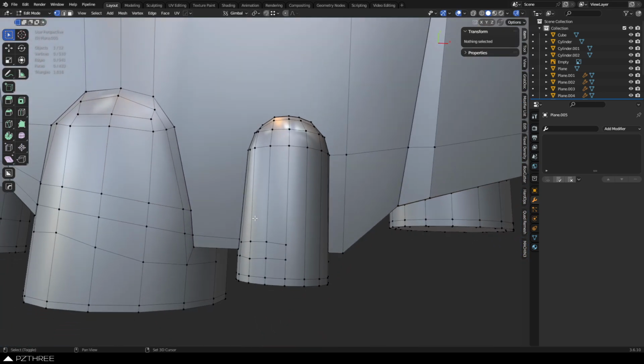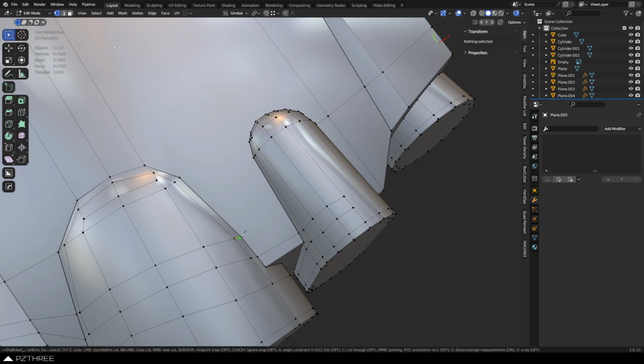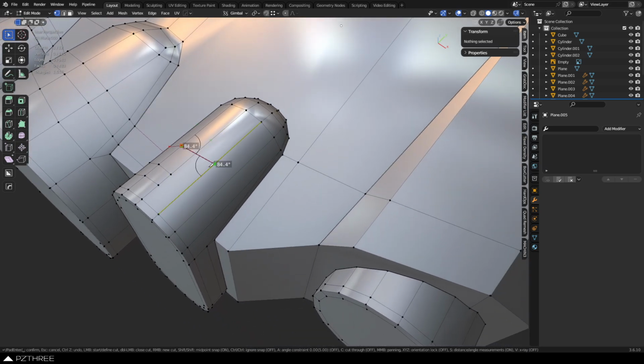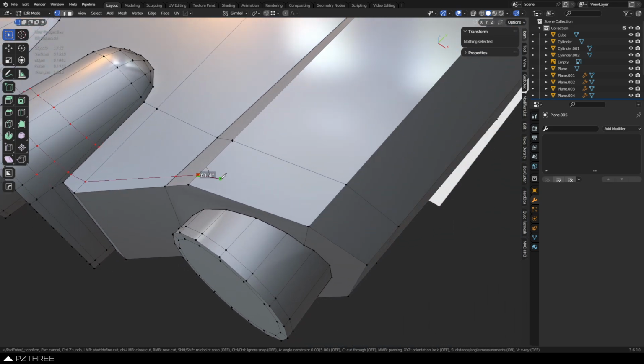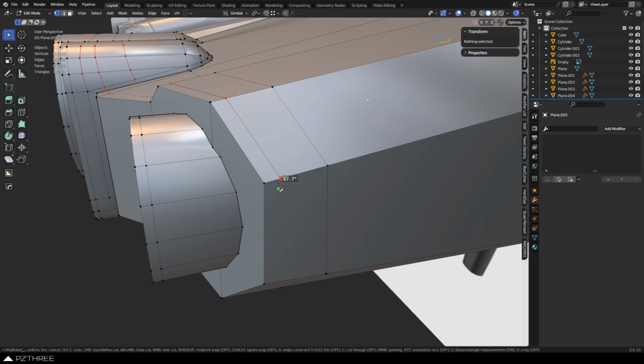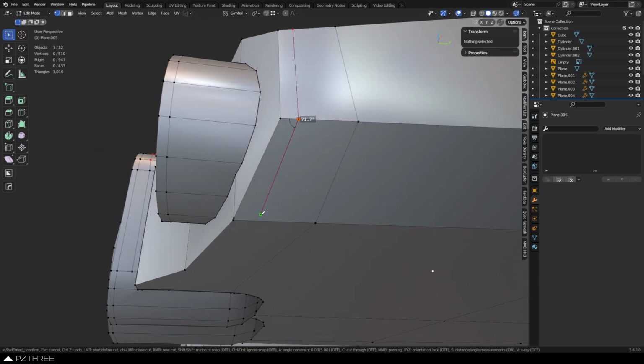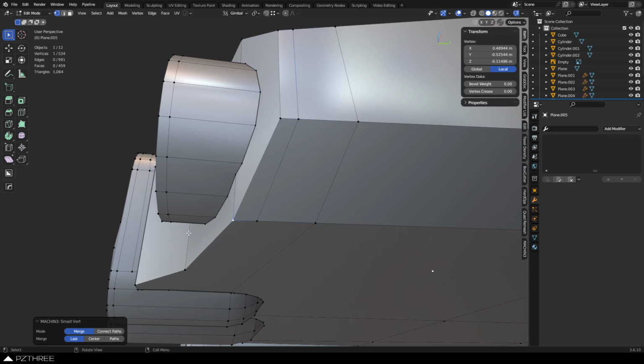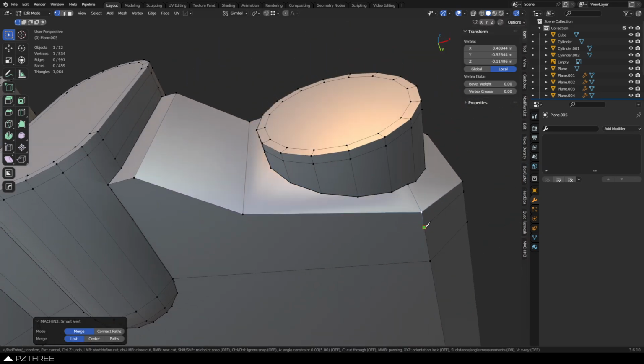You have 2 options there basically. You can do either or. Some guys like to work with basic primitives and take them up after you subdivide them once. So they'll apply 1 subdivision, and then they'll start joining things together with Booleans and whatnot. It makes the Booleans a little bit more challenging to connect back together in some ways, but the benefit there is that you don't have to worry about triangles or n-gons as much, or non-planar faces and stuff like that, because usually the shapes are kind of set in stone and you're only working the edges and the Booleans.